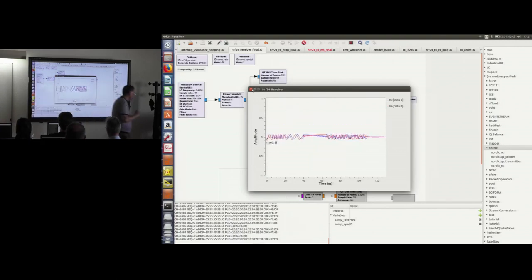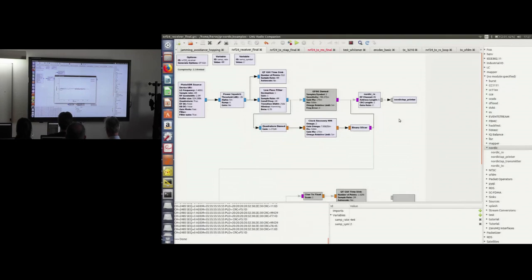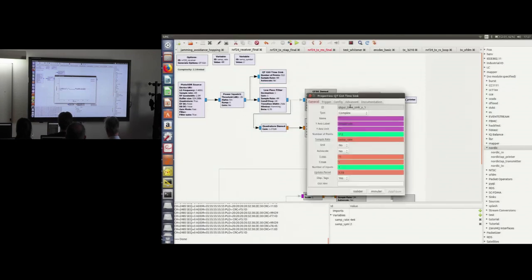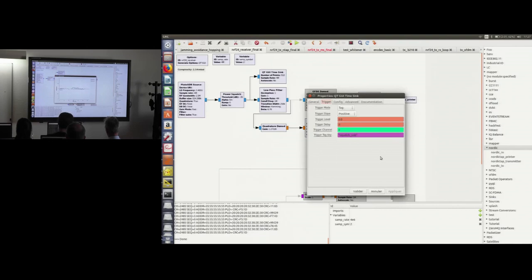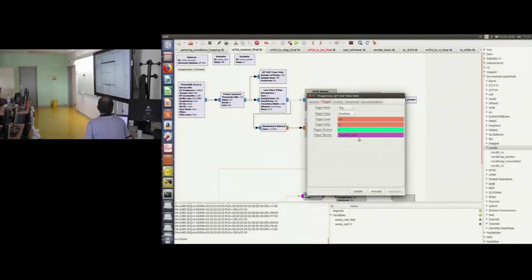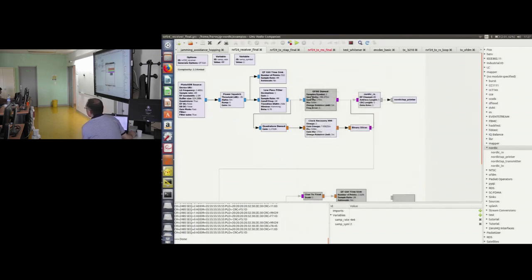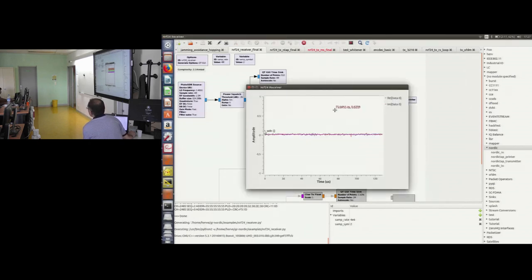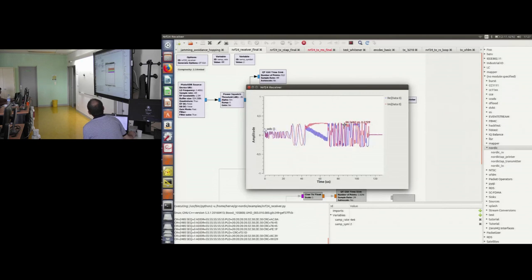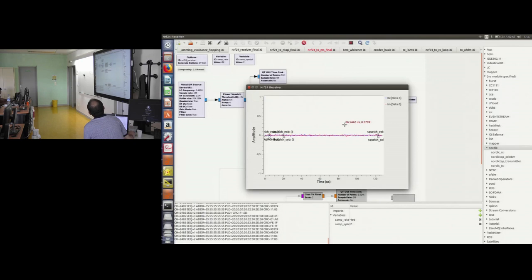Okay, I'll show you. So that's my GFSK packet. What you can do is simply go here. You've got trigger, and my tag is squelch_SOB. So I say I want to synchronize on the squelch SOB. That's quite nice because you see exactly what you want to see and not the rest.